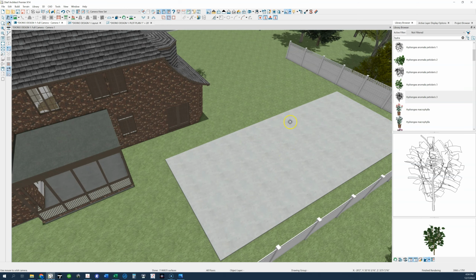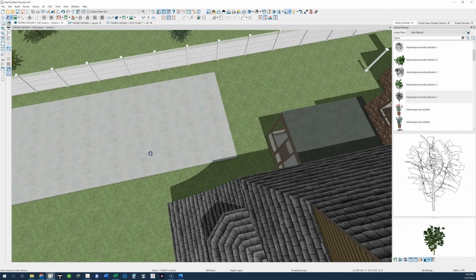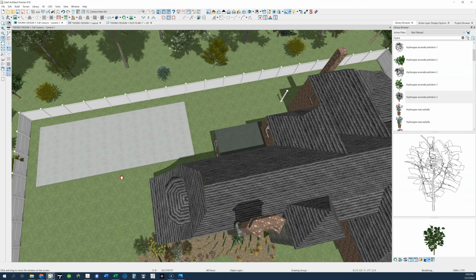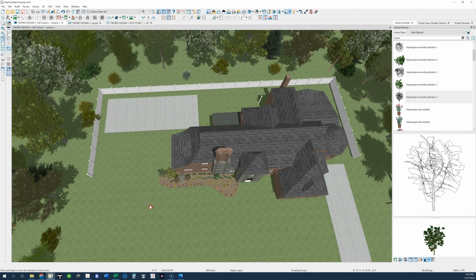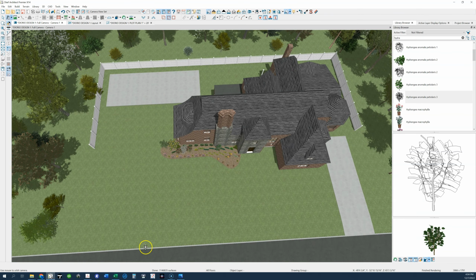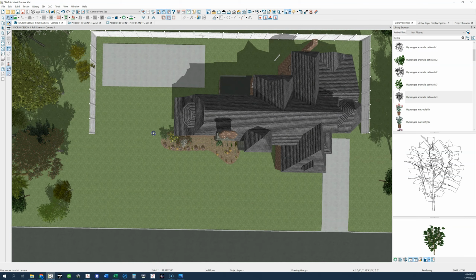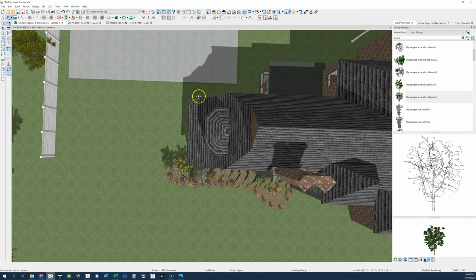This line right here, accessory structures have to be 2/3 of the way back from the front property line, towards the rear. So it would have been originally here, but then I incorporated the 8 feet from the rear of the house also, 8 feet from the main structure.